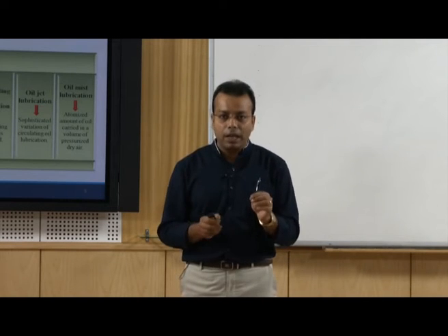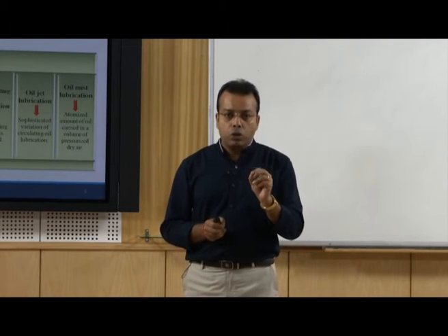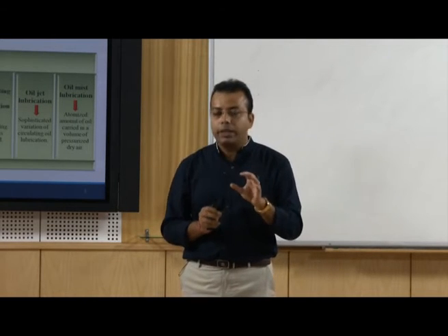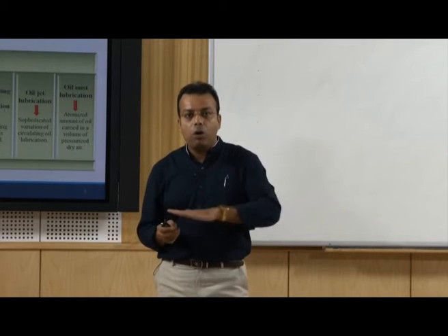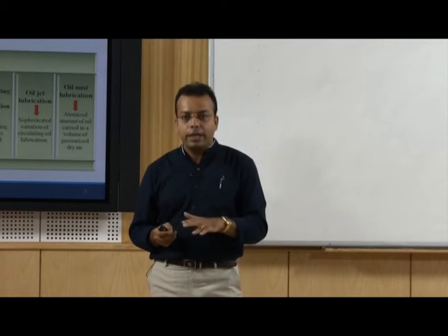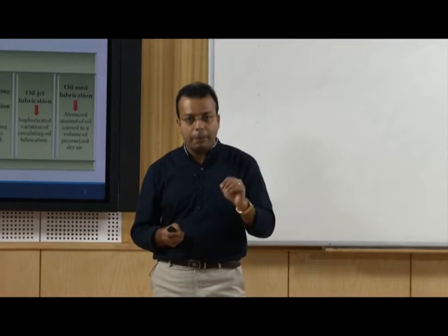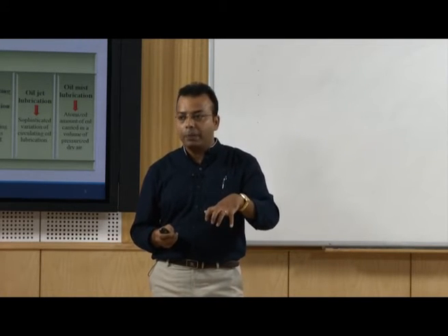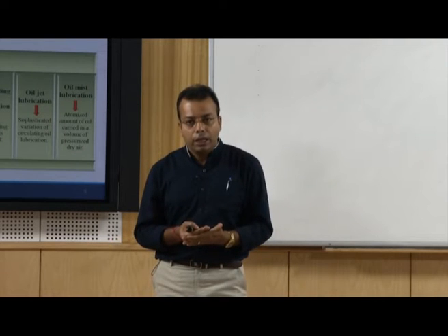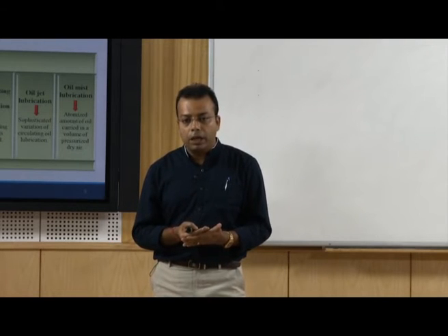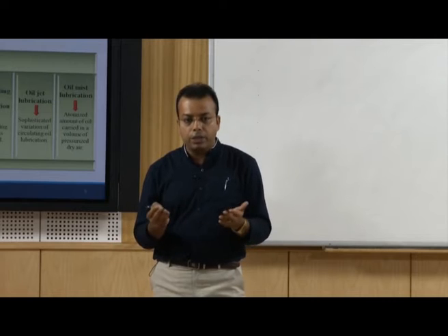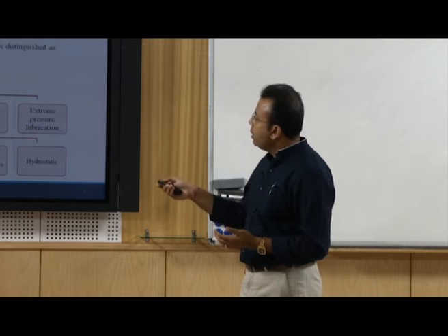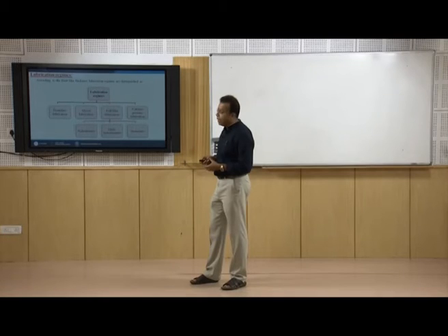Mist is nothing but small droplets. So, with oil we are injecting high-pressure air, so that like a spray the oil floats onto the surface. It is not continuous oil coming, it is like droplets, the oil coming onto the surface in between the mating parts, and it does the lubricating, and it is used for the best lubrication.